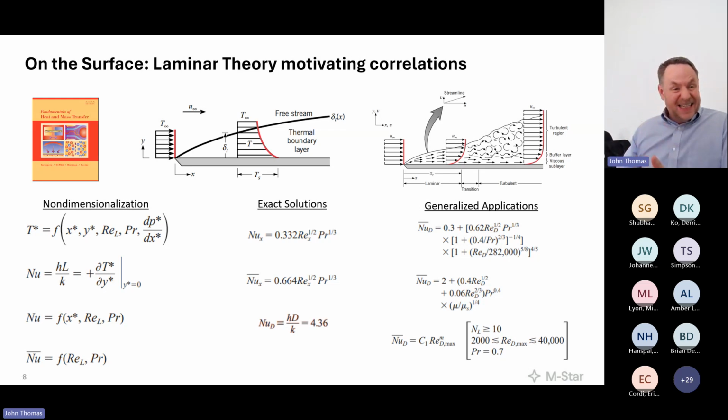It's just a fit. And that's not a bad thing, but we've really washed out a lot of physics as we take increasingly complicated topologies and shoehorn them in through Nusselt, Reynolds, Prandtl. It's not a bad thing, but why, physically speaking, is that 282,000 to the 5/8? Okay, why? Because it fit. And that's not a bad thing, but admittedly, we've kind of lost sight of the physics and focused on fit and exercise, which is useful. These run quickly, but we've really jumped the shark, motivated by a good origin story. We've started applying these things to everything as Nusselt, Reynolds, and Prandtl, and it works, but we've lost a lot of the physics in the process.